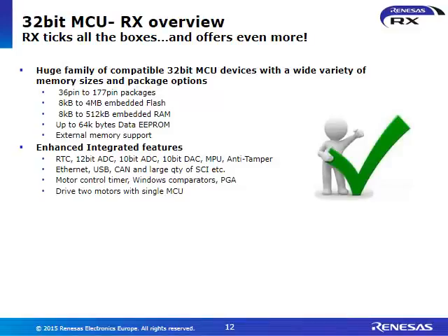It also integrates a lot of different peripherals: 12-bit A to D, DACs, memory protection unit, floating point unit, also Ethernet, USB, CAN, and a large quantity of different SCI channels. It offers you application-specific features like motor control, including window comparator and PGAs. It enables you even to drive 2 motors with a single MCU.